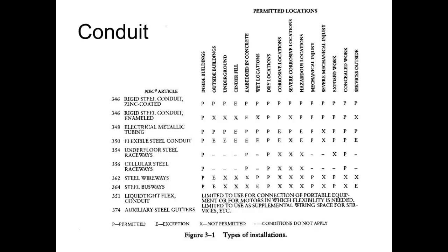No, they don't do rigid metal conduit because, like I said, usually you don't bend rigid metal conduit. You'll cut it, you'll thread it. So you have pipe threaders, and you thread it, and then you put a joint on there, a coupling, to get the bend that you want. So that's the way you usually do rigid.